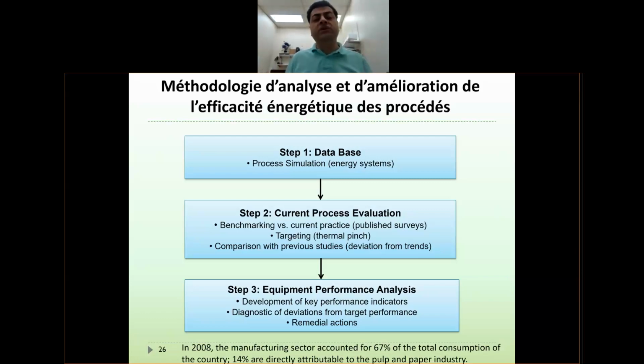If you put a new heat exchanger in the system, you know from the heat transfer course, I guess you remember, that there is a problem in heat exchangers called fouling. When the fouling starts to grow inside the heat exchangers, the heat transfer coefficient is going to deteriorate. So you don't have heat exchange as good as a new heat exchanger. That's why we usually define key performance indicators (KPIs) for each unit operation in the process.